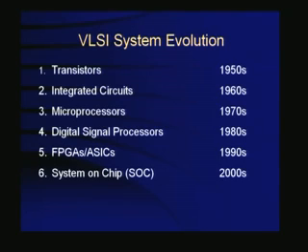So it has the advantages of ASIC and the advantage of DSP, the programmability of DSP and all the architectural, innovative features of an ASIC, both put in FPGA. So FPGA became a very popular device for prototyping or small scale application, universities for example, research. For example, in this course we will see extensively the use of FPGAs. All the examples we will talk about, we will use FPGAs because we cannot make an application specific IC for every application we are going to teach you in this course.